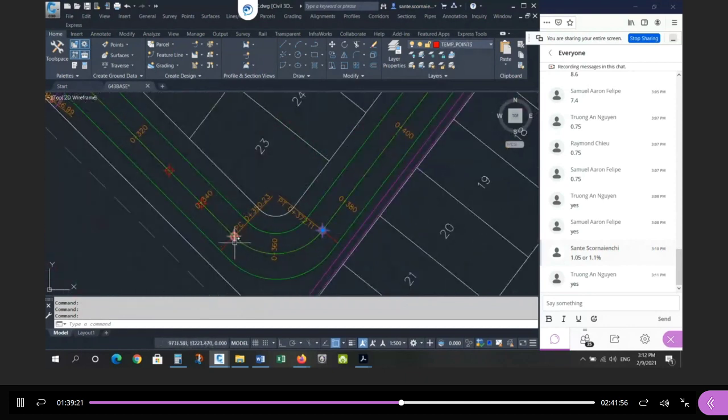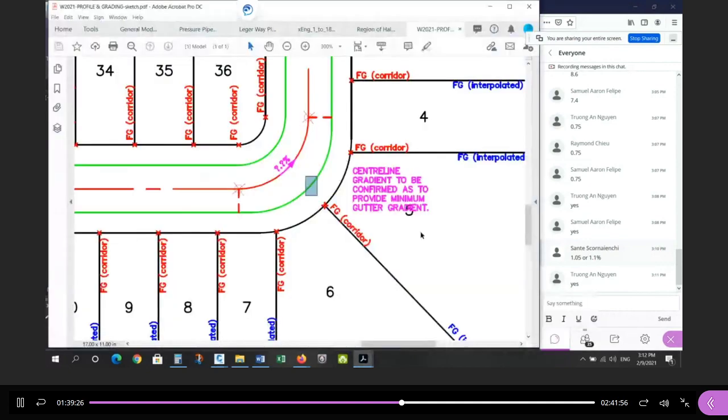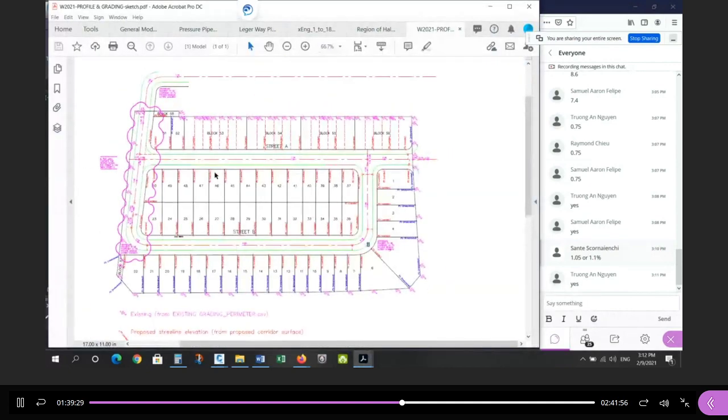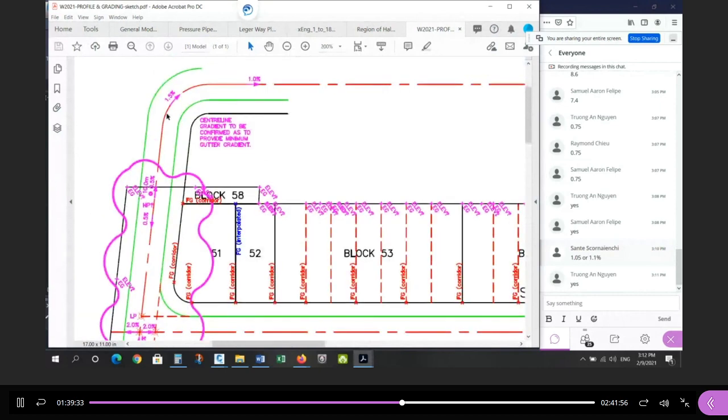between this point and this point. And you'll notice here, it works itself out. In the elbow, according to the profile, the slope in here is already 1.5. The existing profile through here is already 1.5, steeper than 1.1, so I know this elbow is going to work. I'm not worried about this one. Okay, and how do I know that's 1.5?